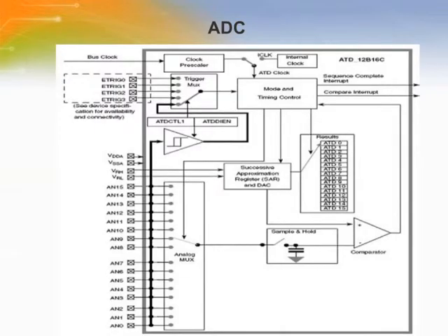The analog-to-digital converter is a 16-channel, 12-bit, multiplexed input, successive approximation analog-to-digital converter. It is structured into analog and digital subblocks. The analog subblock contains all analog electronics required to perform a single conversion. Separate power supplies, VDDA and VSSA, allow isolation of noise from other microcontroller circuitry from the analog subblock.